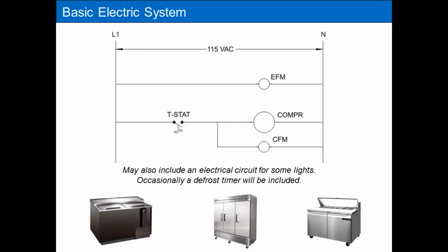Another thing that you'll see according to this wiring diagram is that the compressor and condenser fan motor are wired in parallel, meaning generally they run together. If the compressor is running, the condenser fan motor is running, and vice versa. Now, that's not always 100% true.